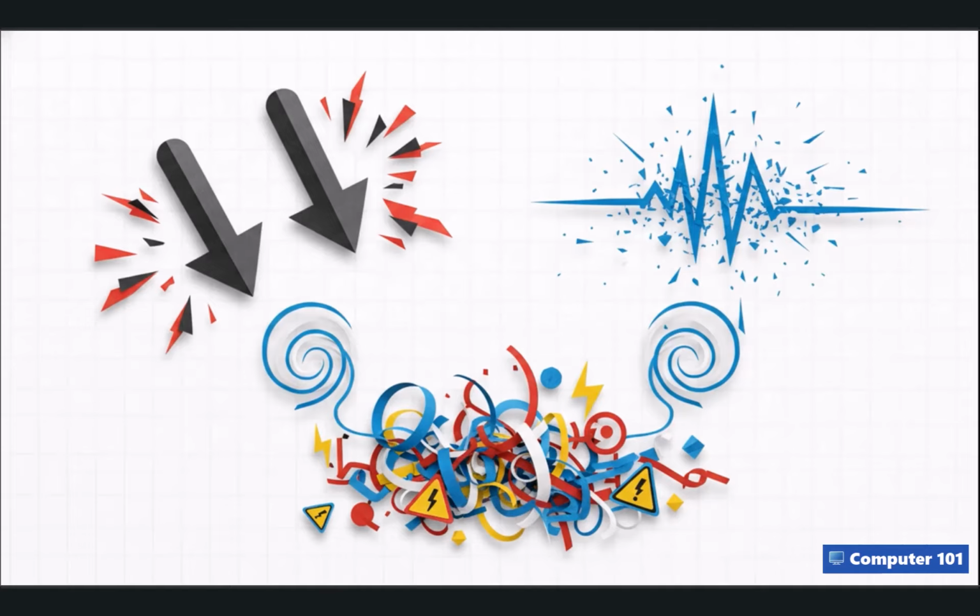There are basically 2 physical triggers for this glitch. The first is what we literally just saw, both inputs dropping from 1 to 0 at the exact same time. The second trigger is if the duration of our set or reset signal is just too short, specifically if it's shorter than 2 times the gate delay, or 2 times T.